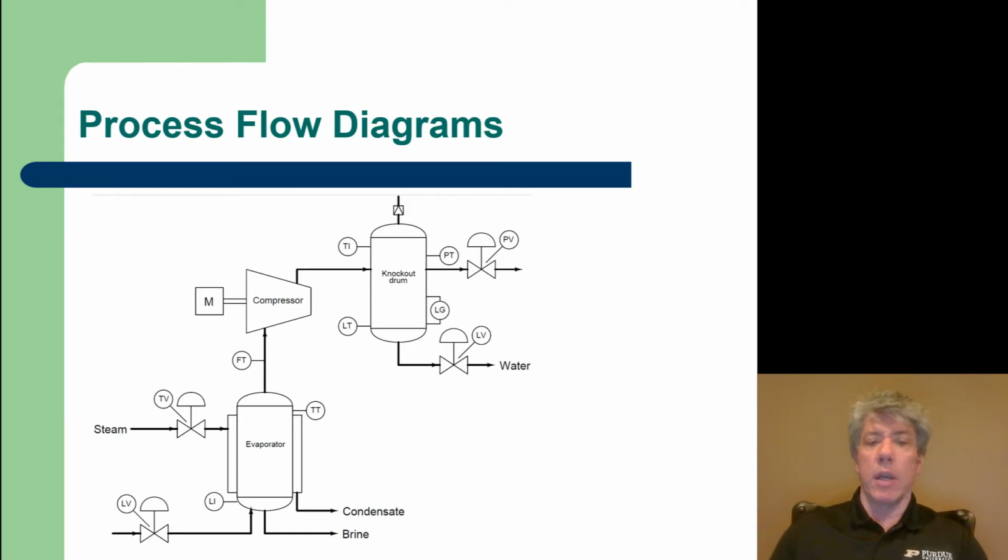So apparently, maybe whatever's coming in here is, I don't know, maybe it's air and water, maybe there's some liquid in it, and the evaporator's job is to warm up that water so that it evaporates. Maybe that's what this does. Anyway, it's called an evaporator, and it has flow in from the bottom that's being processed. Now, the flow in from the left, that steam flow, is a flow that goes into the jacket and serves to heat up the evaporator, and then it comes out as condensate.